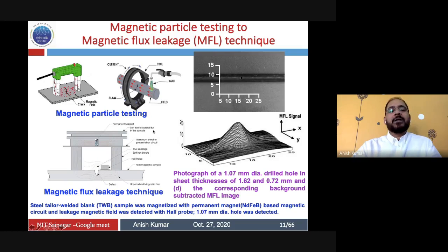In fact, this kind of magnetic flux leakage technique can be used where we cannot go and do the inspection to sprinkle the powder and all. You have the magnetizing unit, and you have the sensor which receives the signal if there is any stray field leaked out. This can be used for large pipe inspection gadgets, which are used to inspect long oil pipelines.